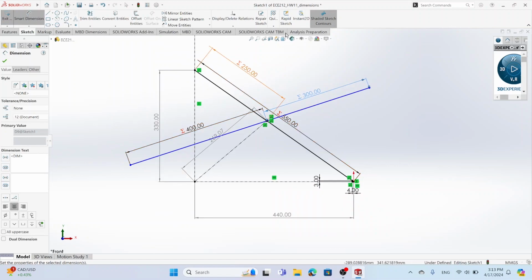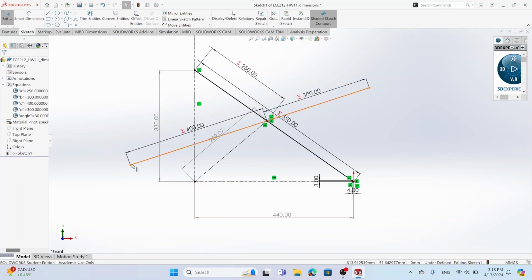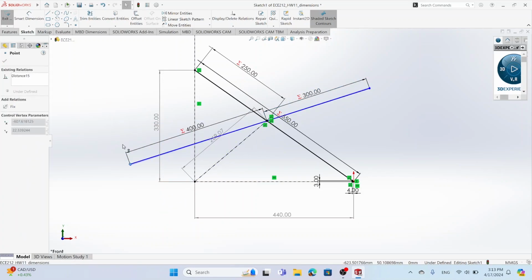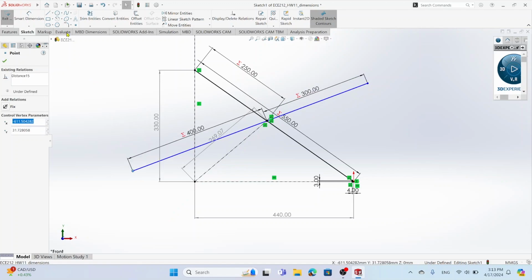If I go too fast, go back on the video a little bit slower. We just missed something, you see it's blue. Blue means it's not constrained. So if we grab that, we see that we can still move, turn. Okay, we need to fix this rotation.